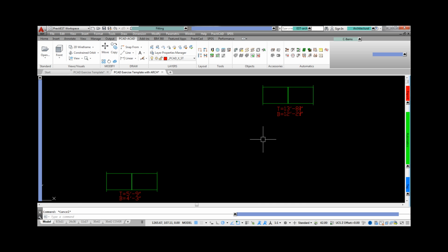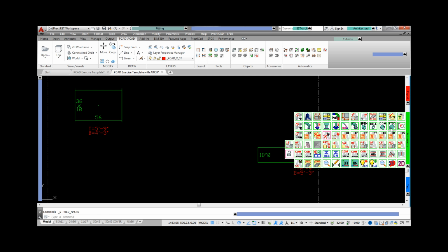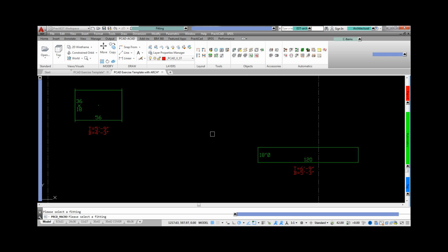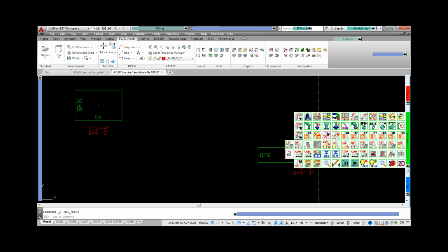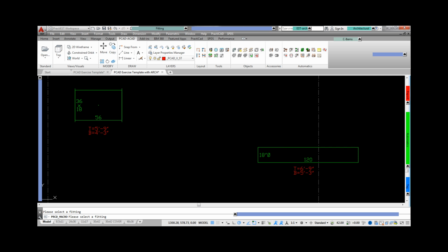In this next route, we are telling PractiCAD to use 45-degree elbows specifically. However, we can choose a large variety of different scenarios to make sure that we get the angle we want. Notice here as we route between 2 points using several different options including 90s, 30s, and 45s. Also using this feature with round duct or pipe, PractiCAD will calculate the roll angles needed to make the connection. This makes it easy to look at different scenarios to see which one would suit you best.